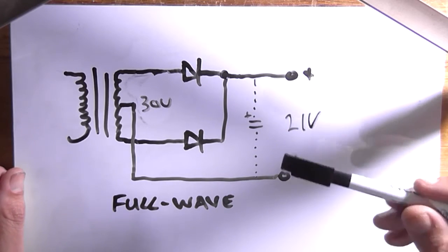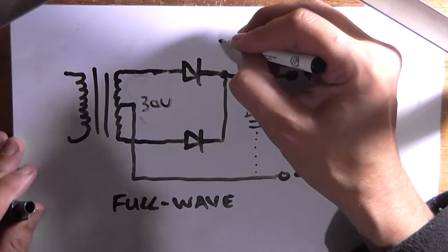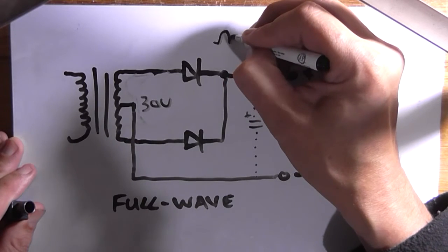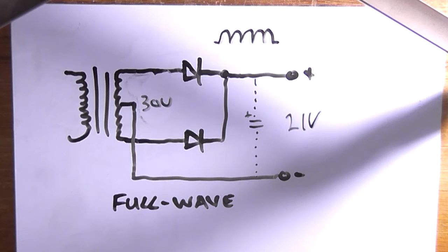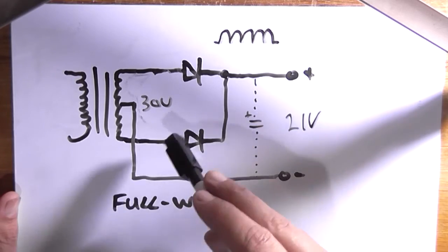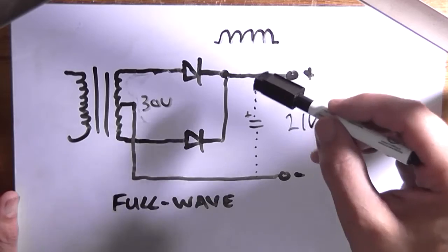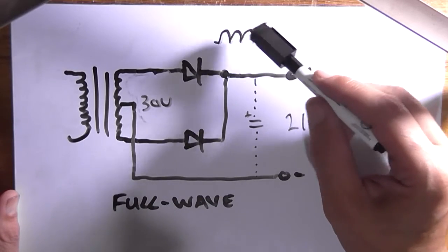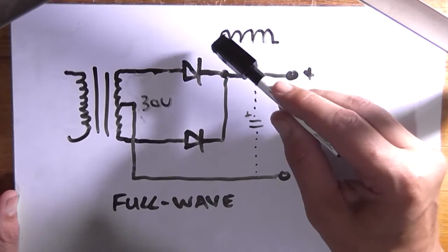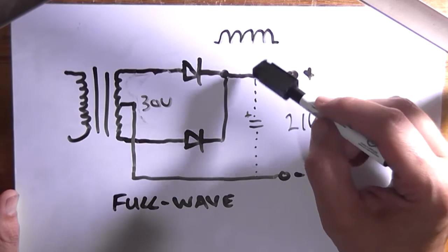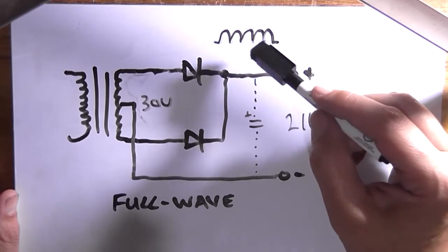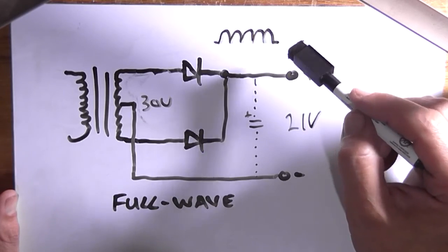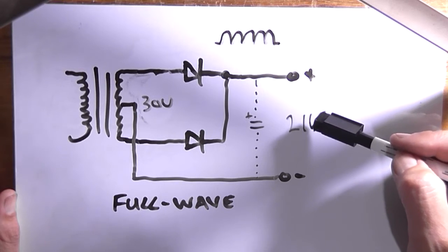It just doesn't work. But the advantage is now our waveform on our oscilloscope screen will have no missing cycles because the other diode fills in the other peak that's missing, and so that's why it's called full wave, because all the peaks are accounted for. And this is assuming you don't have a filter cap. This is why it's drawn in a dotted line, because with that capacitor in, that would be almost a flat line, and the output voltage would be 21 volt.